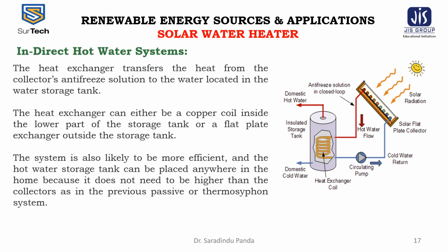all year-round operation in areas where the temperature falls below the freezing point, as well as protecting the system from corrosion of the collectors by untreated tap water containing gases and various dissolved salts. The main advantage of a forced circulation indirect hot water system is that an existing domestic water heating system can easily be converted to solar heating of the water just by adding a flat plate collector and a single pump,